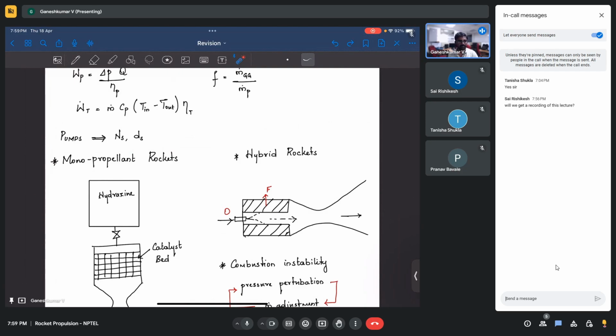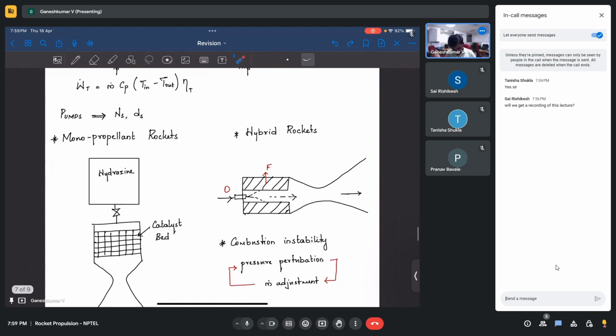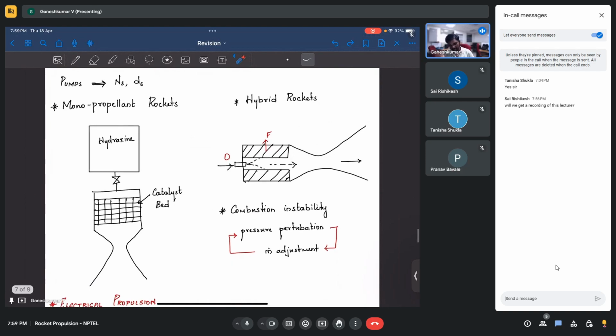Otherwise, solid propellant and liquid propellant are the same in terms of finding the performance. The only thing is the liquid propellant has an injector, where fuel and oxidizer come in, and it forms a sheet of propellant layer, then forms droplets, and the droplets start to burn. And in solid, you just cast it and put it inside, and the solid keeps on burning.